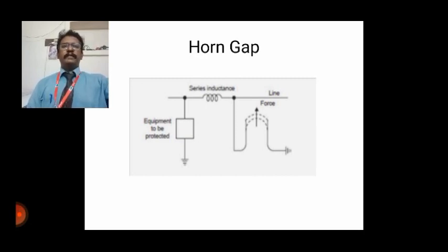Next, you can see here, whenever a surge voltage exceeds the breakdown value of the gap, a discharge takes place and the energy content in the rest of the wave is bypassed to the ground. An arc is set up between the gap, which acts like a flexible conductor and rises upward under the influence of electromagnetic forces, which normally happens in the diverters. Thus, the length of the arc increases, which eventually blows out and does not sustain.